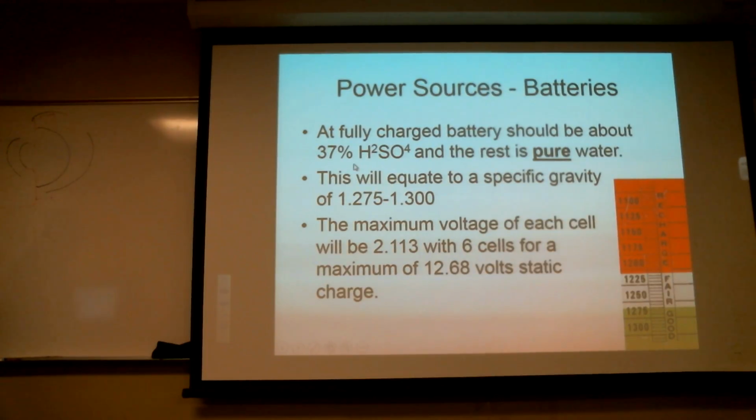Well, there's really two potentials going on when they blow up. One blow up is a combustion, hydrogen lighting. The other is the pressure vent doesn't work, it pressurizes and blows up. Hard to say which one causes it. As it outgasses, the pressure's going to increase if it can't relieve it.